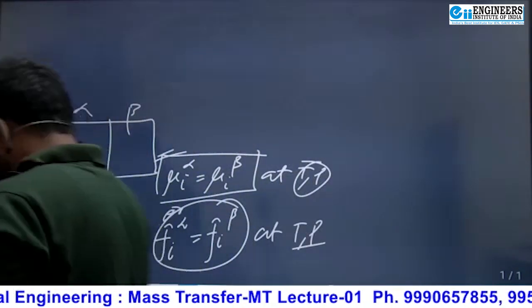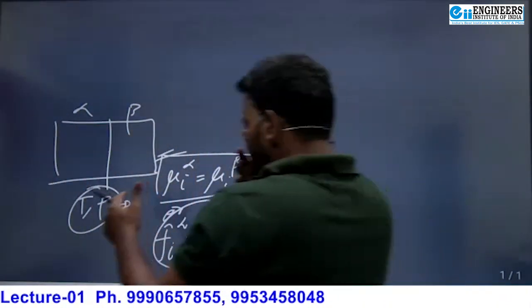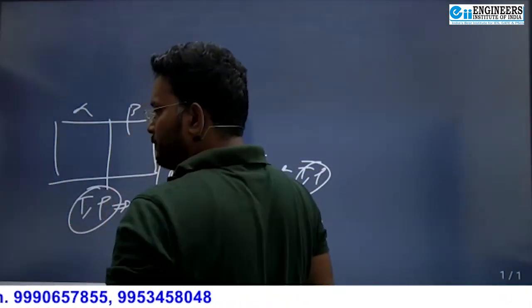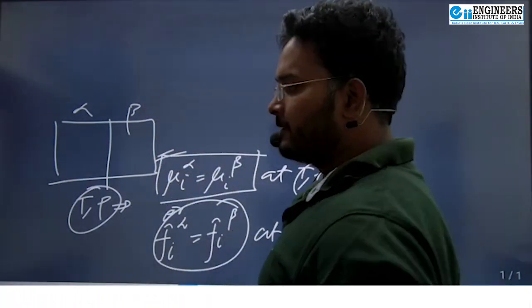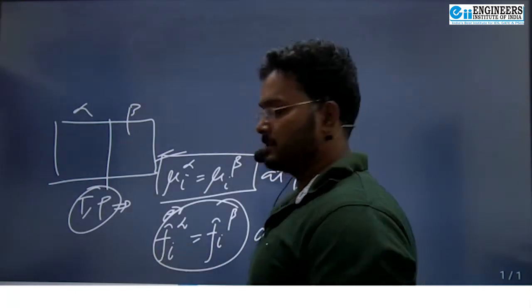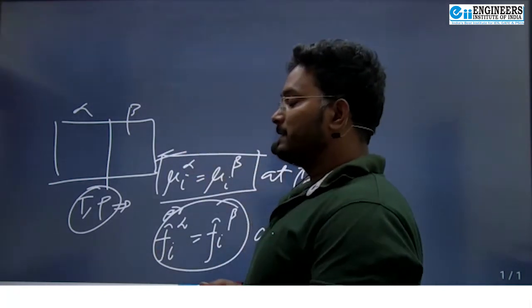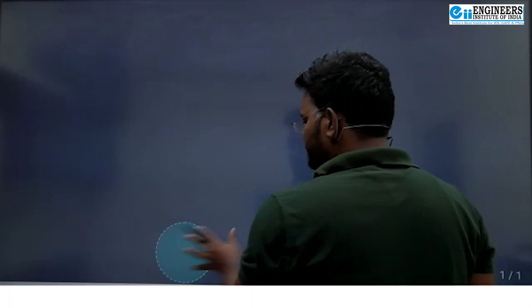Is this clear? Now what is the similarity between heat transfer and mass transfer? The similarity is that just like in heat transfer the driving force is the temperature difference, similarly in mass transfer the driving force is concentration difference if I am talking about single phases. Clear? But at the same time there is a difference, and what is it? Try to understand here. At the interface there is no discontinuity in the profile. That is very, very important, sir.